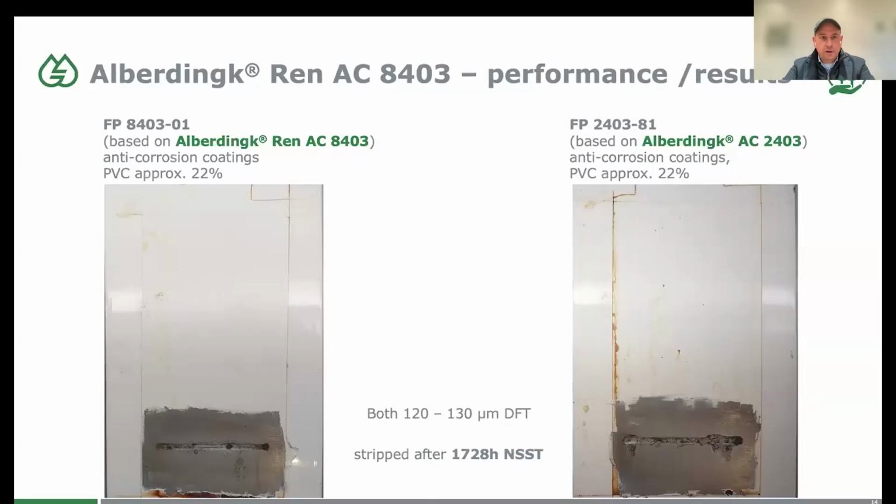So if you have a polymer in a molten state, it will have a higher water absorption than a polymer in a solid state. So if you have a test, which like here operates at higher temperatures, you can reduce the overall water absorption by having a portion of polymer which has a lower water absorption.